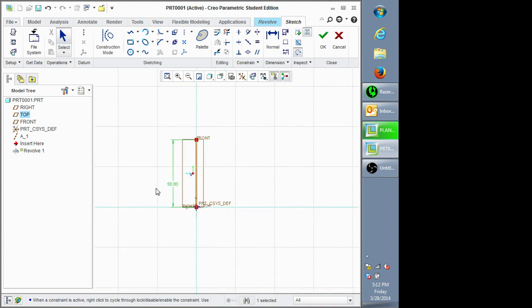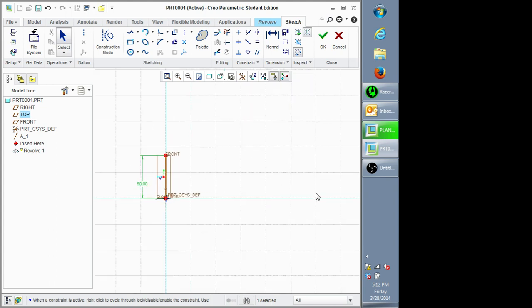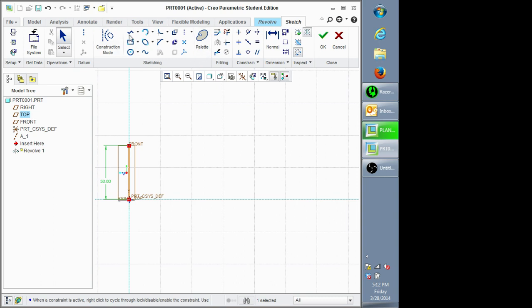Notice my zoom in for you zoomed in a little too much for me, where I couldn't see it, so I'm zooming out a bit. Now I want to create the bottom edge, which will control the width of the nose. So let's go to the line tool again, select the bottom corner of the origin, select it, and it should automatically lock onto it.